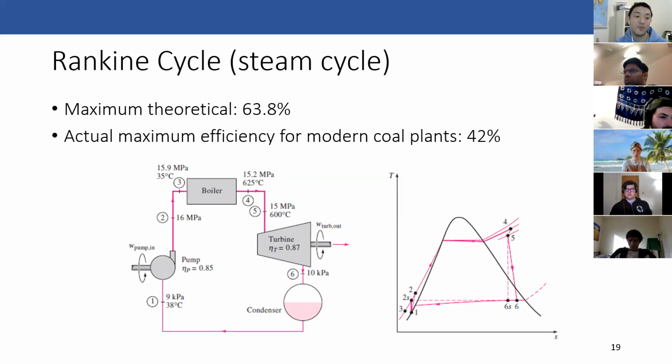It's not in a liquid form, it's in a gaseous form. It gets sent through a condenser where the water collects and is sent back into the boiler to heat up again in the combustion cycle. And that water is actually in this closed loop, and I'll show a diagram of that in a moment. This particular type of cycle is known as a Rankine cycle.